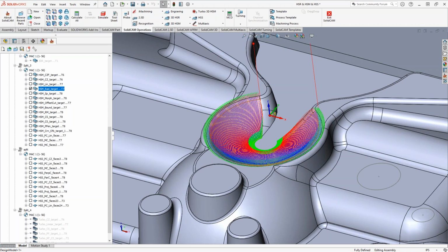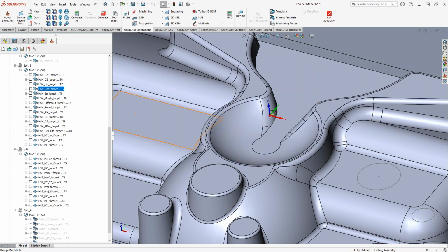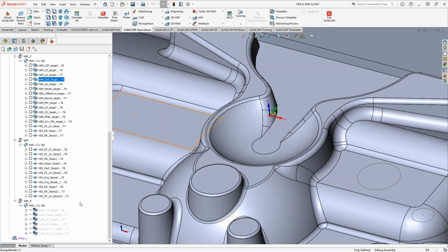And one thing to really get that wow factor, this kind of goes back to our boundary machining, but if Mark on a flat face was to do that as a linear surface, kicked it off at a 45-degree angle, and then did a sketch inside there and broke up that surface, what you can actually do is engrave or have your company logo on there, but do the same toolpath at a different angle, and you'll get a really cool projection of that surface having your company logo on there as well.